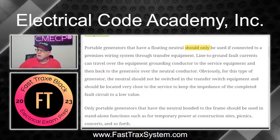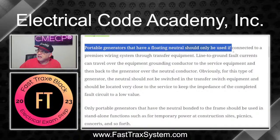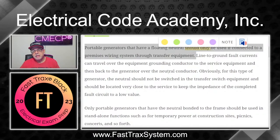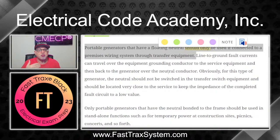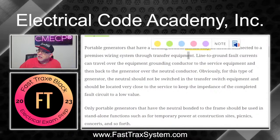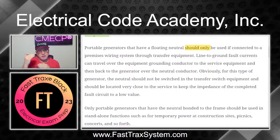All right. Next, portable generators with the floating neutral should only be used if connected to a premise wiring system through transfer equipment. Okay, so if you have a generator that is a floating neutral type generator, then you should make that application through a transfer switch. Okay. Now, because if it is floating neutral, by the way, then you've got the separation, right? You don't have any jumper between the neutral and the frame. Okay. That type of scenario.